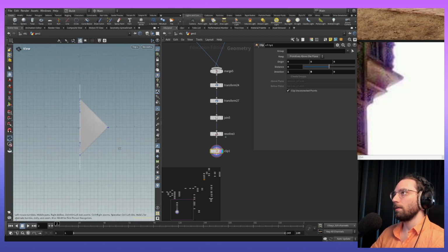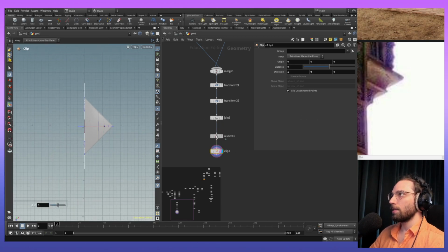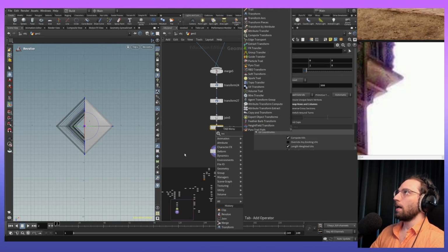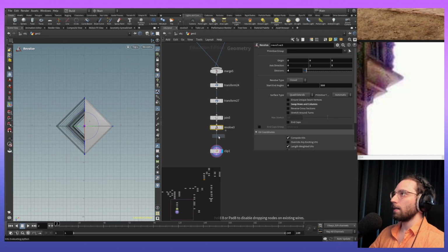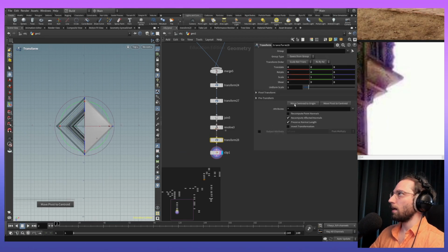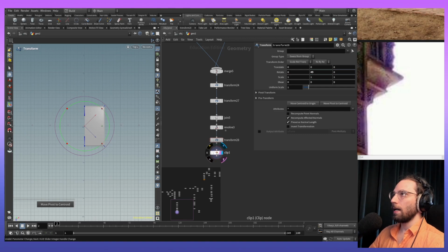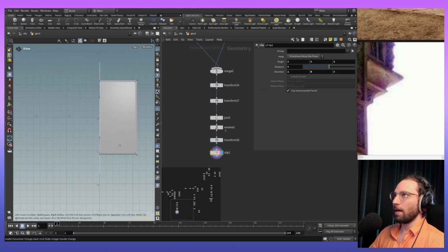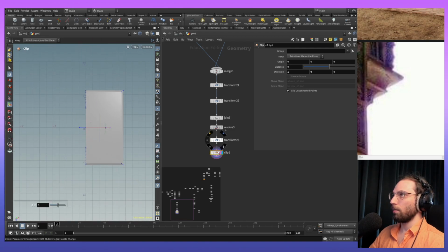That is looking better. I will take the revolve and add a transform from that. Transform my friend, yes, correct. Connect me right there and give me a rotation of 45 degrees. Not in that axis, but maybe in this axis. Here we go. And now the clip will help us determine the exact angle we want to work with.